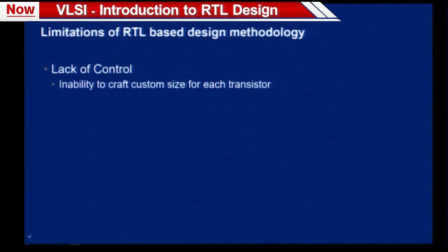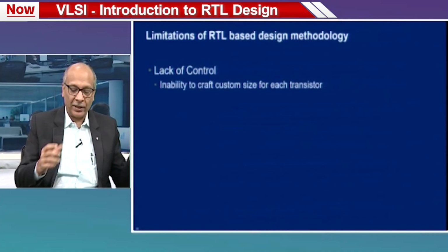Some more limitations: lack of control. You cannot control at each transistor level. So, that is why you cannot do custom sizing of each transistor, and this is why high performance data paths usually go through custom design mechanisms rather than RTL based mechanisms.